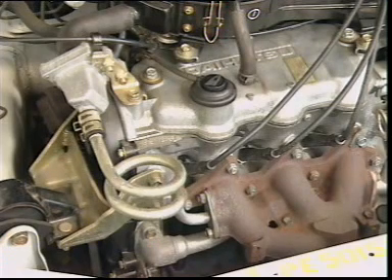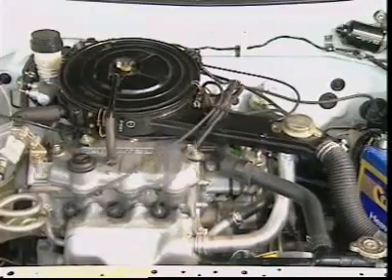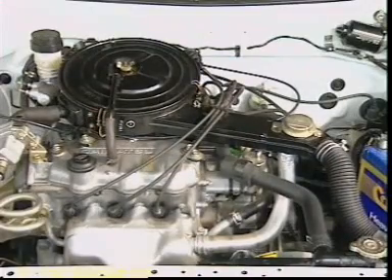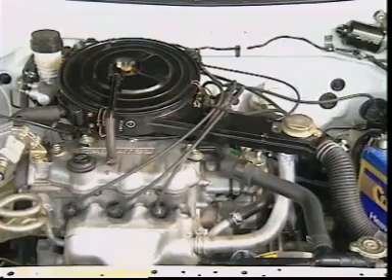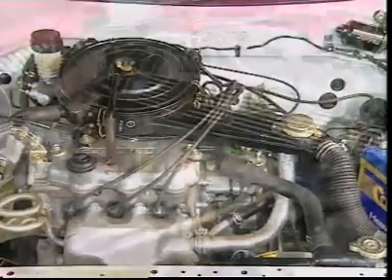The pulse air method uses the pulsations of the exhaust gas to open and close a reed valve. It admits air into the exhaust manifold in short bursts. Air drawn from the air filter enters the exhaust manifold. This method suits engines with 4 cylinders or less, because their exhaust pulsations are further apart.